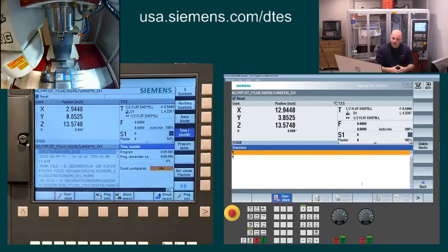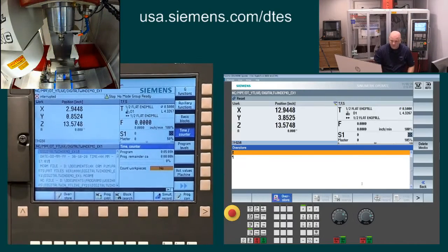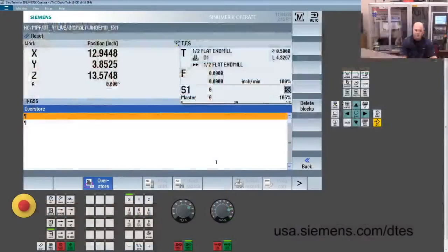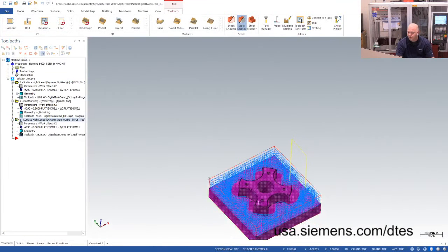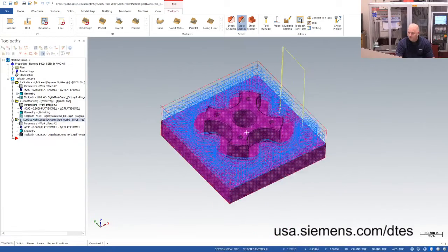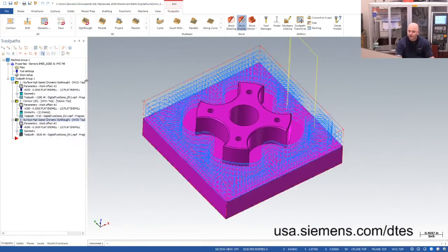So from there, as we expand on this, and I'm going to e-stop the machine so it gets a little quieter in here, I can start to explore this even further. If you start to look at some other toolpaths, let's say I looked at more of a trochoidal style toolpath, once I get to a scenario where the toolpath cycle time is getting longer, I'm going to see that differentiator between the estimated cycle time and the real one. But wherever I get scenarios where I have a lot of axis reversal, it really becomes apparent.